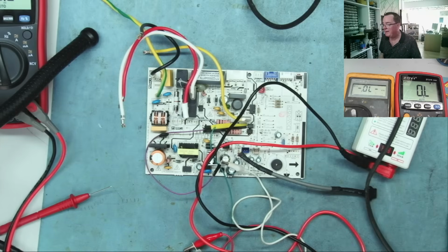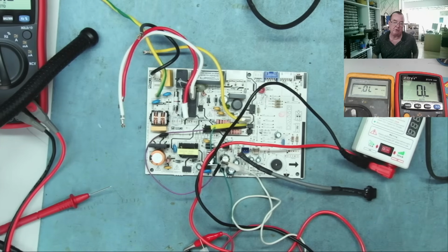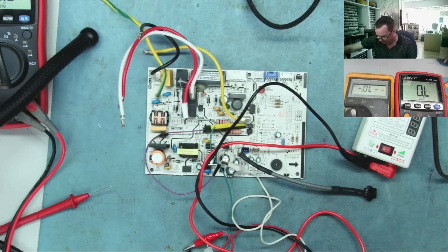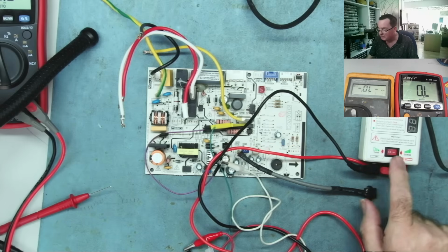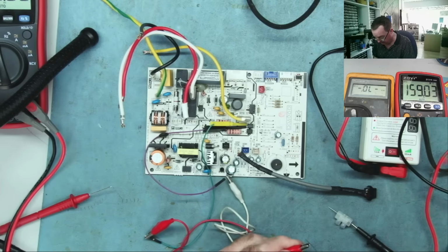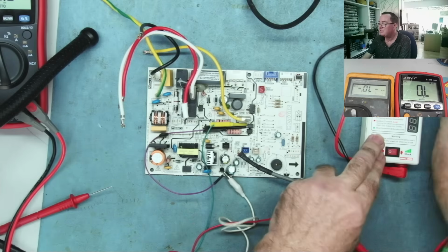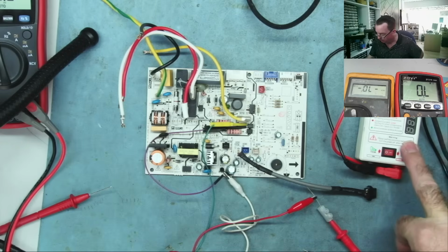You could use your bench power supply with a resistor, like a 1K resistor or 200 ohms or whatever you fancy, something like that. Probably 1K is good enough on 5 volts, you could do it that way. Well, I use my backlight tester, so this is a switchable one, it's set to 1 milliamp. I connect it to my optoisolator. And this has enough power to drive this, so this should say 1 volt.